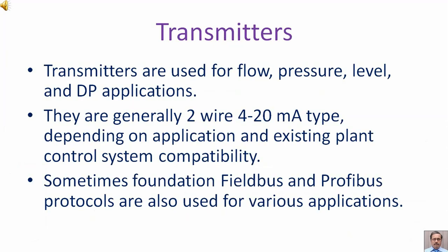Transmitters. Transmitters are used for flow, pressure, level and differential pressure applications. They are generally 2-wire 4 to 20 milliampere type, depending on application and existing plant control system compatibility. Sometimes Foundation Fieldbus and Profibus protocols are also used for various applications.